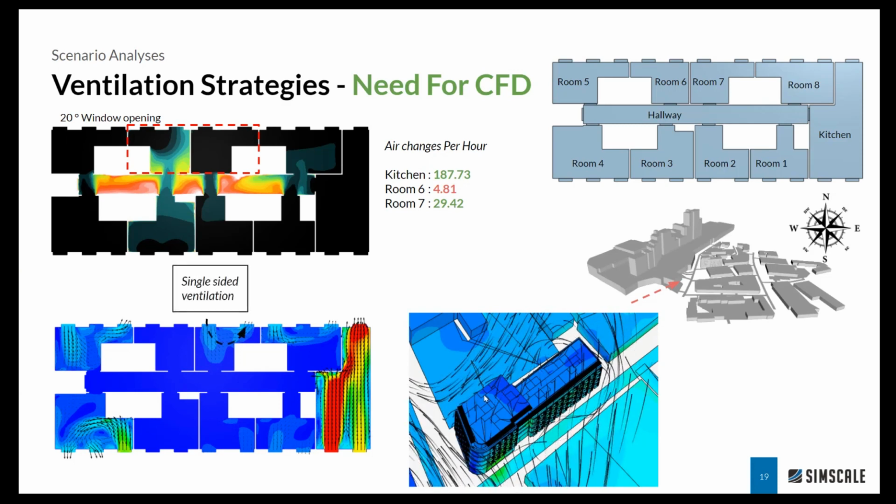And you can also notice something happening on the other side of the building, where the air actually passes through and then creates a recirculation zone exactly at this location. And if you consider a window at this location, you can pretty much imagine that the air is going to go through the window and recirculate out of the window if the other window is open.